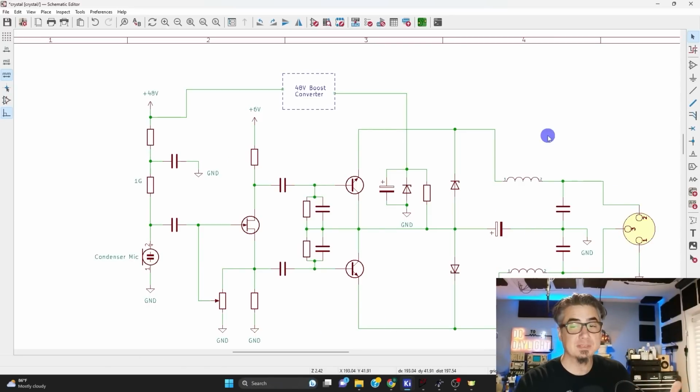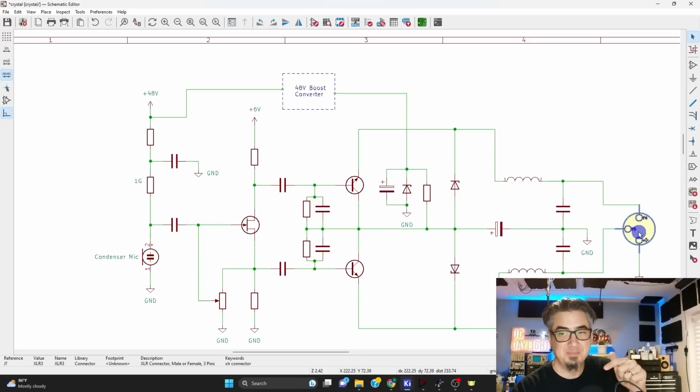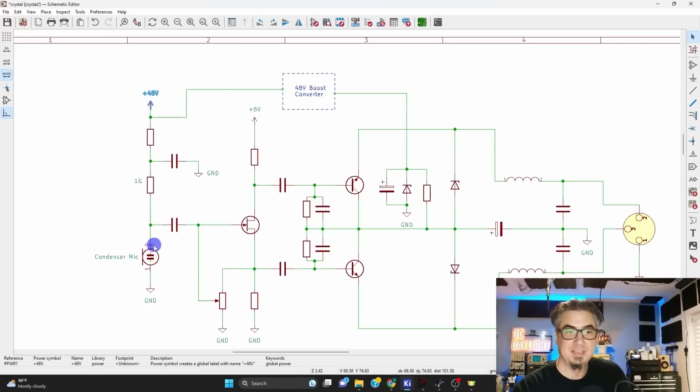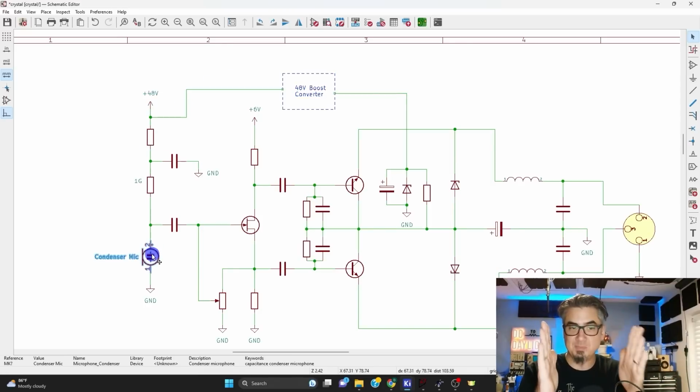So the way they're doing it here is a little strange. They're taking the phantom power, that's 48 volts already, into this circuit, then they're using a Zener regulator to get 6.3 volts from it, and then they're using their own boost converter. There are a lot of capacitors in there to provide that 48 volts that the condenser needs to build up a charge on its plates.